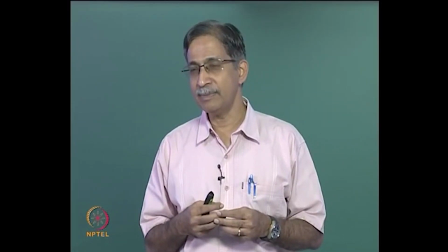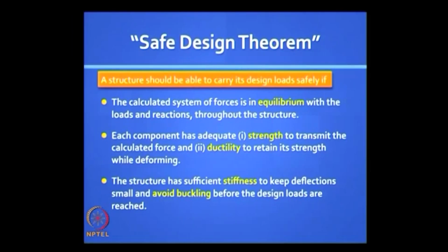In reinforced concrete especially, it all depends on your design of those sections so that you have this plastic rotation capacity and you have adequate ductility for that hinge to stay on, resisting a certain ultimate moment and redistributing the load effects to other locations. So this is something that has to be ensured.